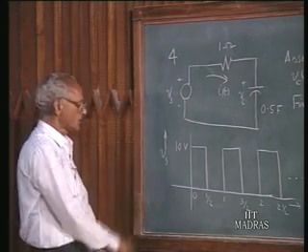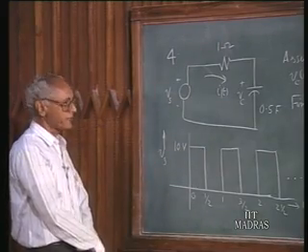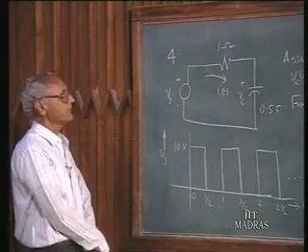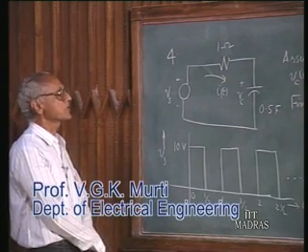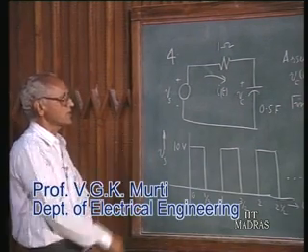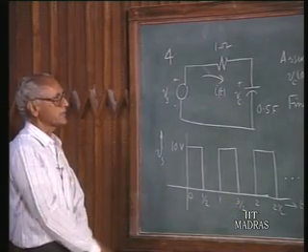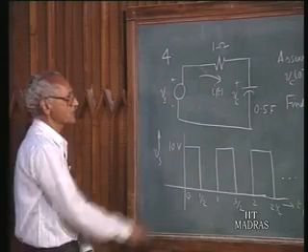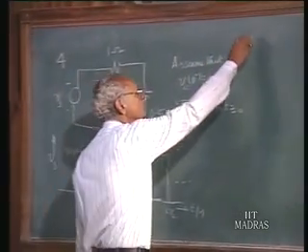So you must find the Laplace transform of that, use that, and get an expression for I(s), and you interpret the I(s). You will have e to the power of s factors also in that. When you find the inverse Laplace transform, you get some delayed versions of certain quantities. You interpret them suitably and give an expression for i(t) in the final result.